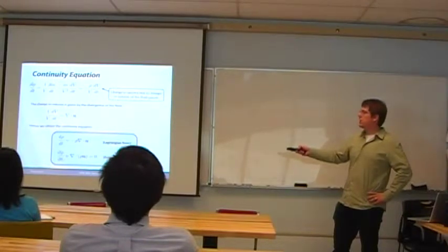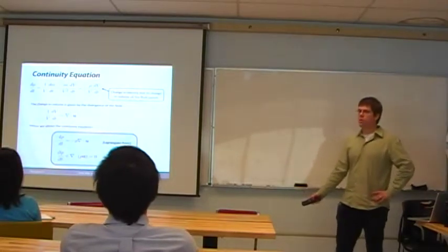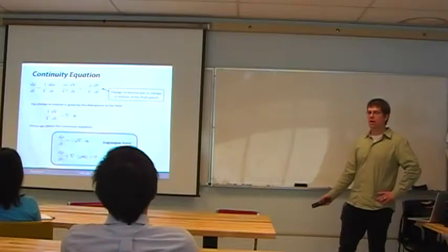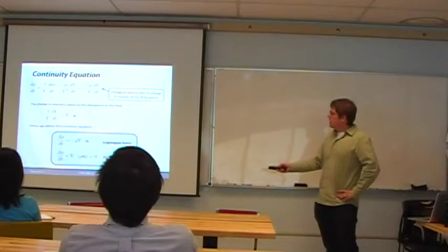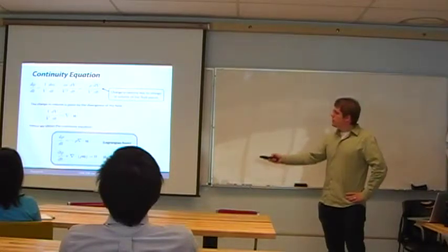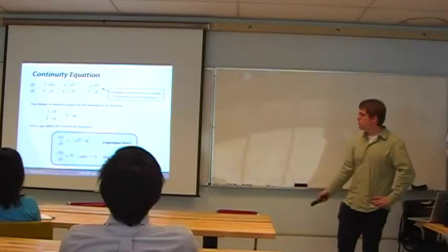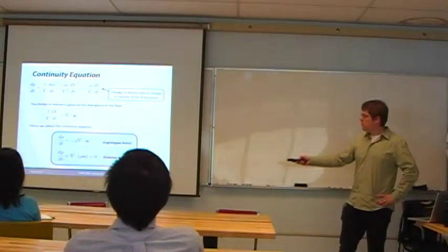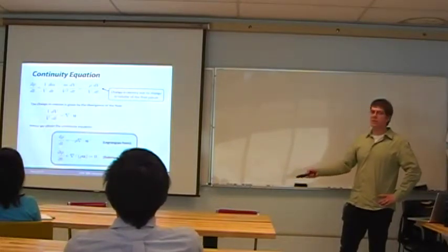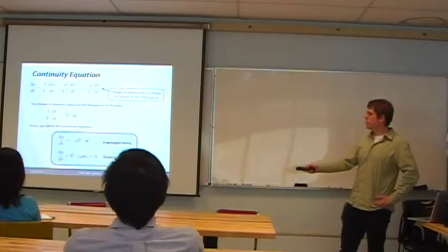You can verify that the units are correct in this expression. The V's cancel out, and instead you have 1 over the time unit on the left-hand side, and on the right-hand side you have a spatial derivative of the velocity. So 1 over length times length over time, and you get 1 over time again. So substituting that in, we get the Lagrangian form of the continuity equation, which represents the change in density following the fluid parcel as simply negative rho times divergence of u, and the Eulerian form, which can be obtained by applying the material derivative to the left-hand side and combining the two terms that pop out of that, looks like this.